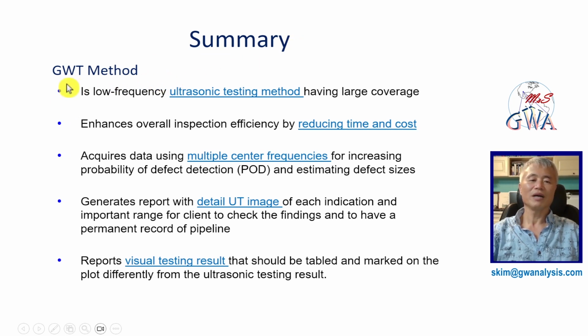I presented 5 key items. First, the guided wave testing method is a low-frequency ultrasonic testing method having large coverage. Second, enhance overall inspection efficiency by reducing time and cost. And third, acquire data using multiple center frequencies for increasing the probability of defect detection and estimating defect size.